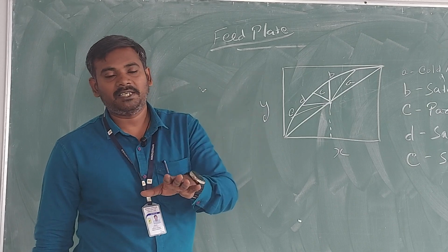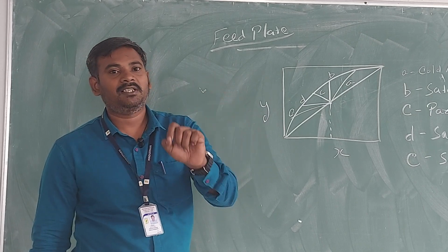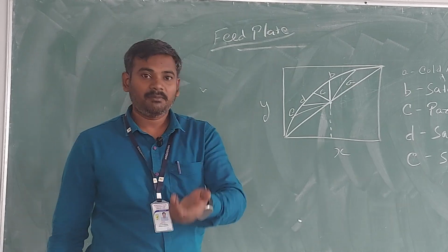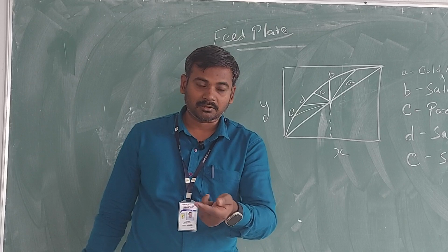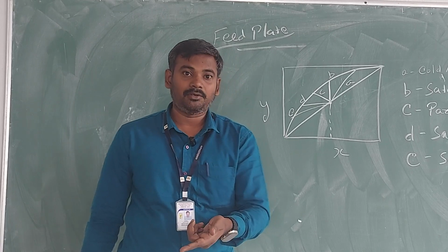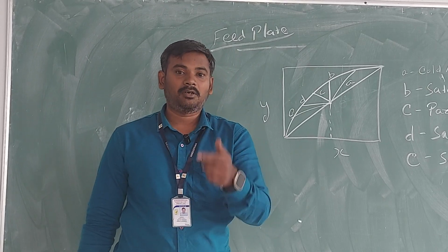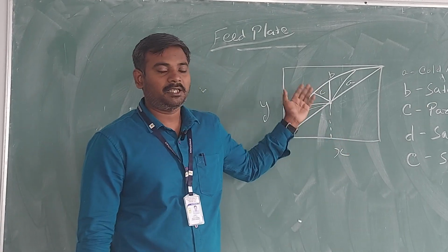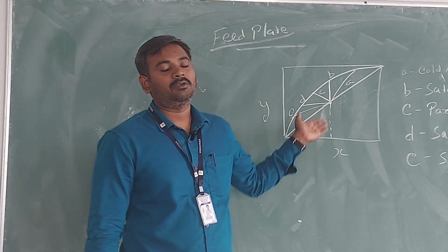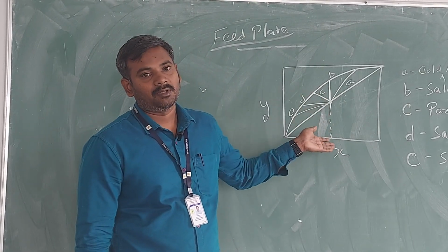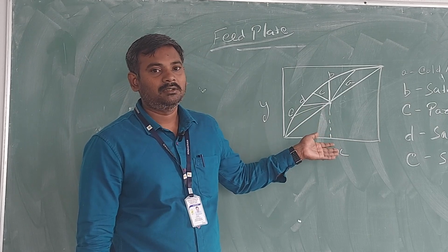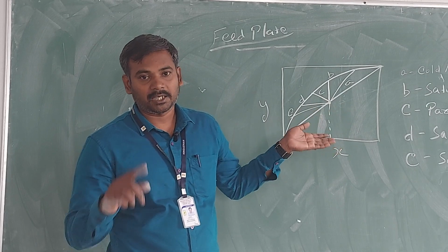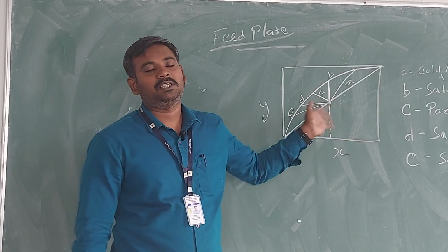The question will be given such that your actual reflux will be some multiple of your minimum reflux ratio. So for calculating your minimum reflux ratio, you have to calculate your reflux ratio. For that, you have to understand the concept of the feed line, that is Q. Depending upon the conditions of the Q line, you have to draw in your graph sheet, calculate your R, then calculate your RM, then calculate your intercept XD by R plus 1, and calculate your number of theoretical plates.